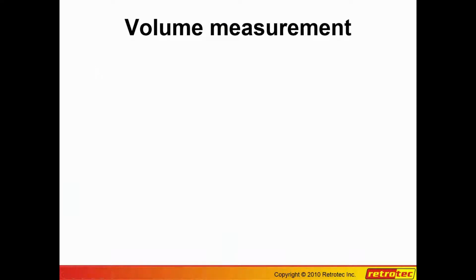So let's take a look at volume measurement. In a recent comparison study, of a relatively simple, straightforward building, we got 6 extremely experienced testers, I mean the best of the best, and they went in there and they measured both the volume and the enclosure area of a fairly straightforward building, and the variation in their volume was, I think, in the neighborhood of plus minus 5%.